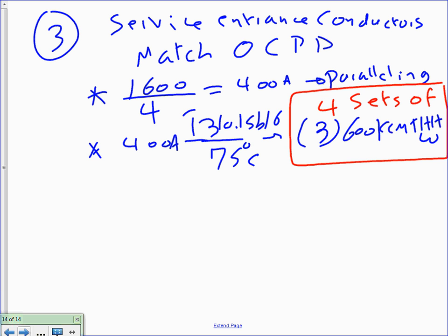Now, Darren, you're a journeyman. If I give you this info, would you be able to put PVC and pull these runs with the type of insulation and the size? He's saying no. Didn't you guys go to the same apprenticeship class? So it's going to be very, very explicit when you write your information: how many conductors, what insulation, how many runs.